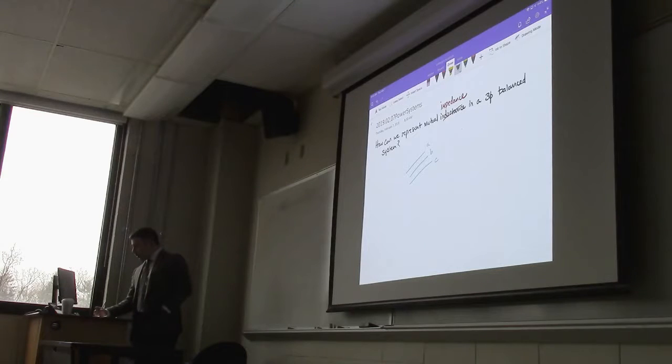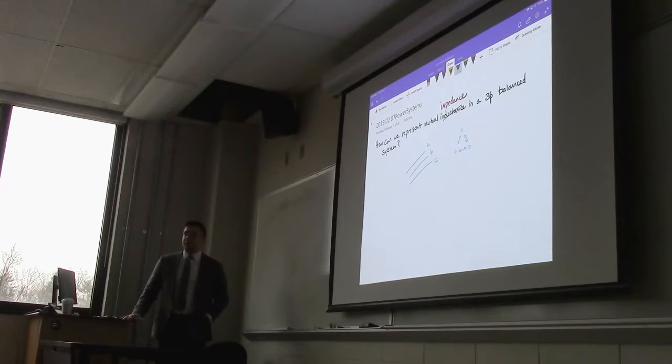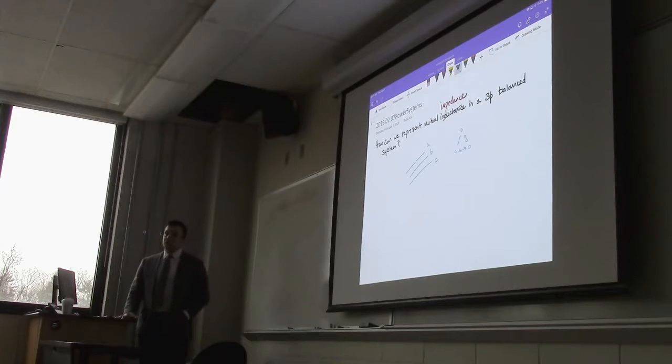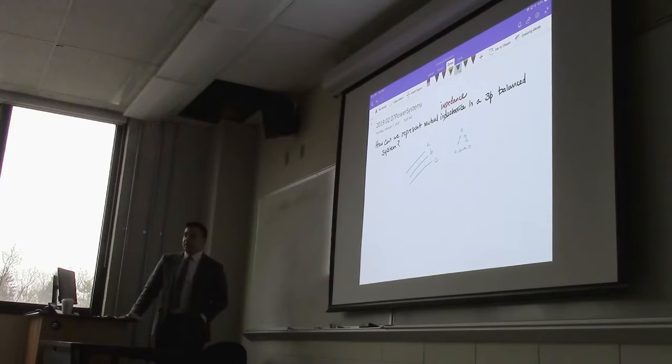One would be to use a spacing like this, where as opposed to putting them flat on the horizontal plane, we can space them like this so that the mutual inductance will be the same for all three of the phases with respect to one another. That's not so much used in the United States. You see it more in Europe. It was used in the Soviet Union.